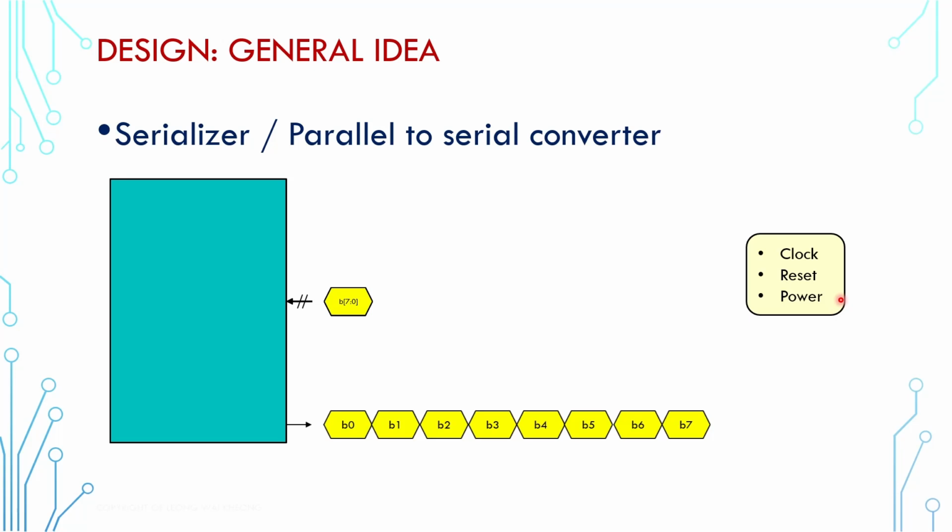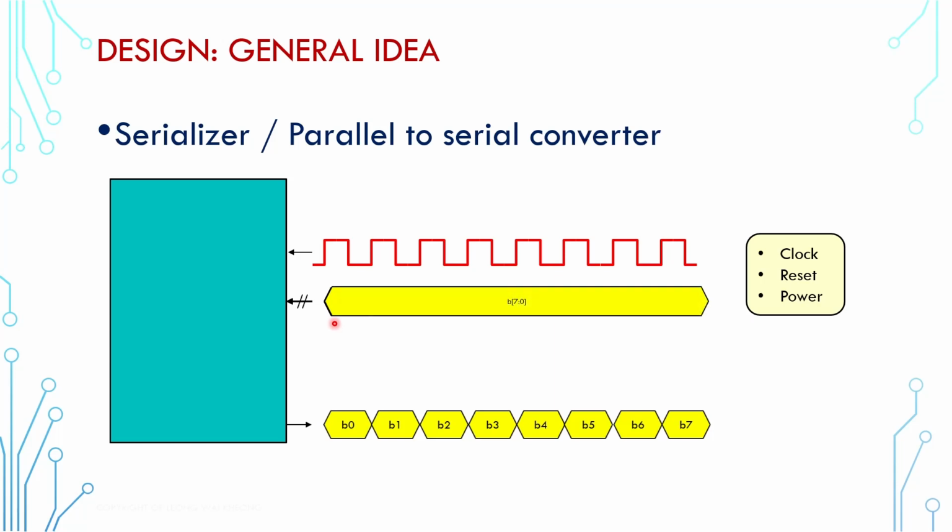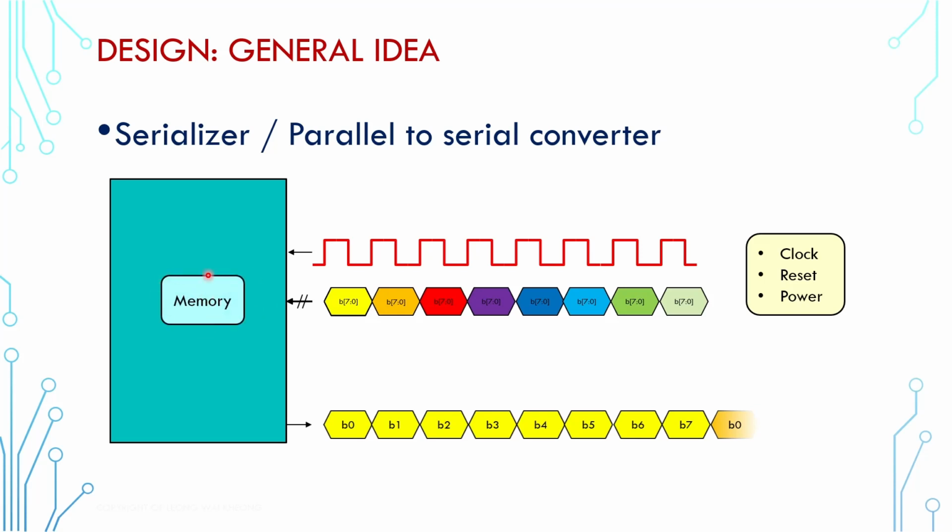For starter, how many clocks are there in the design? If there is only one clock, it takes one cycle to sample in one input data, and it takes 8 cycles to send the output data. In these 8 cycles, do we need to hold the input data constant? Let's say we don't need to do that. Does that mean we can send several input data back to back? We know one input takes 8 cycles to convert, so the pending inputs will have to be stored in the design before they are converted, and that means they are memory elements, and the design therefore is more complicated.